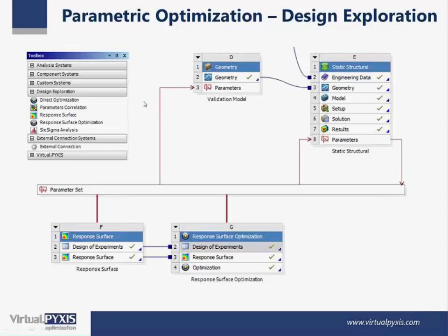is a specific model inside a Workbench workflow, and there are some options. For example, direct optimization. In our case, we have 2 input parameters, the radius and extrude. If you use direct optimization, the software needs hundreds of design points to get the best, which is the minimum weight and stress constraint. So this direct optimization takes a lot of time for this case.